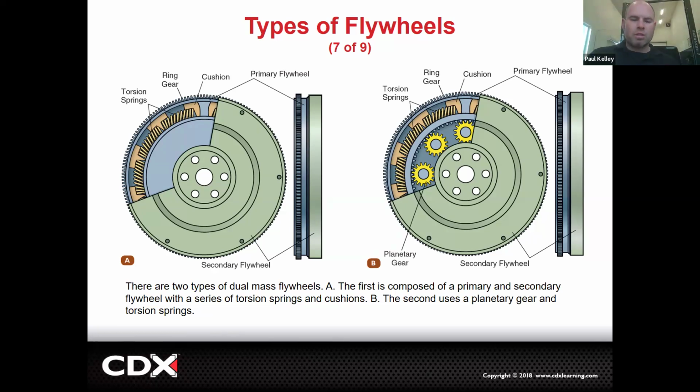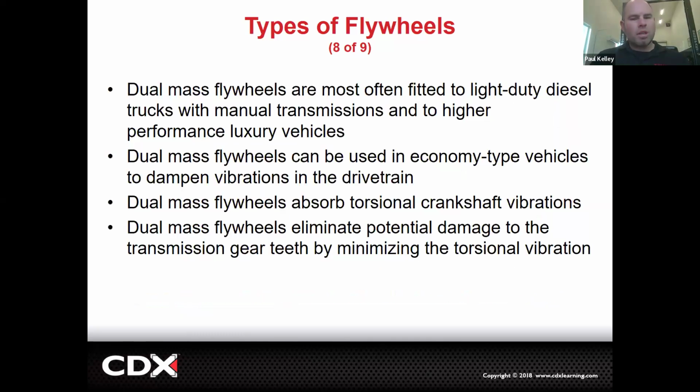I would look it up on service info. If it has a dual mass flywheel, I build it into the price of the job and tell them, hey, if I get in there and the flywheel's good, and it probably won't be, then I'll save you the money. Okay, then I won't put it on, but it's probably going to be messed up by the time you're doing a clutch. Makes sense? And so anyway, that's kind of like what they go on, especially with diesels, high performance, but luxury cars. So that sounds weird, but I'll give you what I mean by that.